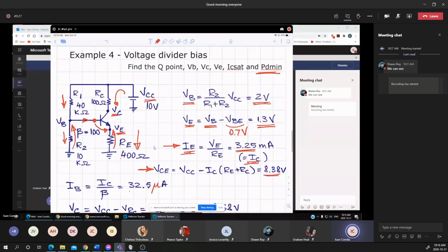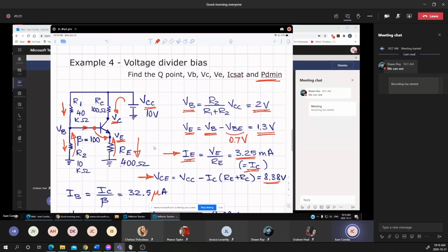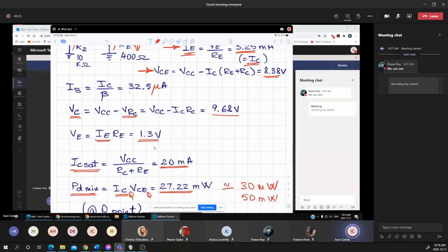That's why in choosing the transistor, I'm looking for the collector current, that's the maximum collector current. I'm looking for the VCE maximum voltage that can be applied. And another parameter is the PD, or the PD max. Keep in mind that always look for the current, look for the voltage, and the power dissipation.